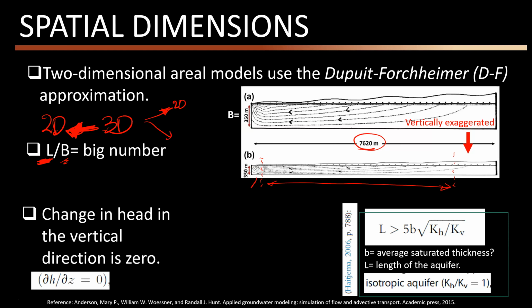Okay, we will have a little bit of a problem at points closer to the boundary conditions. For example, if there is a stream here and we want to model the streamlines exactly at points close to the boundary condition in a stream, maybe it is not a good idea to consider 2D models. It is better to analyze it under a 3D coordinate system because the vertical components and vertical gradients are high, and it's better not to ignore them.